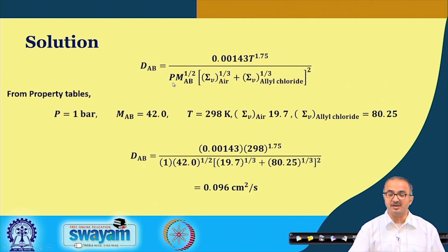It is also a function of molecular weight, because the heavier the molecule, the more effort it takes to diffuse, so its diffusivity will be low. It is inversely proportional to the square root of the molecular weight. These two expressions represent the molecular volume, and it is also inversely proportional to the molecular volume raised to 2/3.